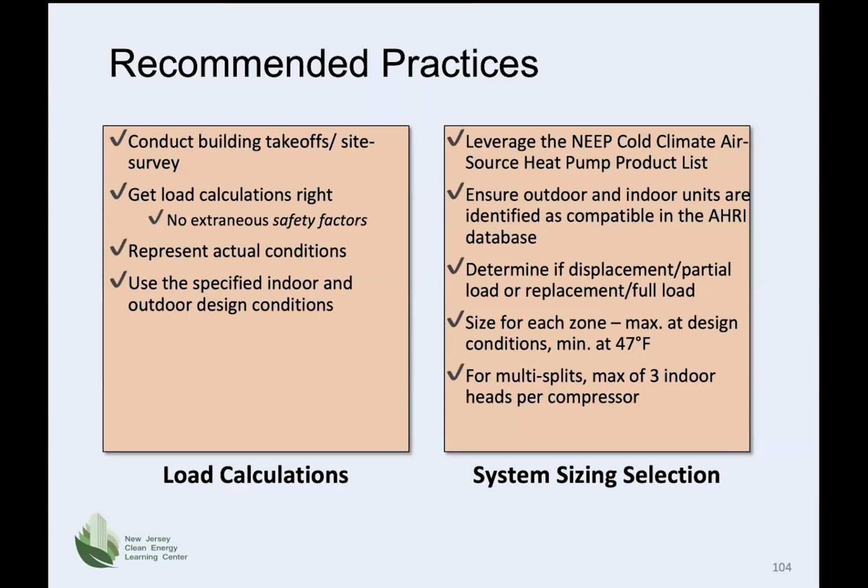And then determine whether you're going to displace part of the load or whether you're going to replace it in full, whether you're going to retain perhaps the legacy system and use it as a supplemental or backup heat, or if the entire house is going to be heated with the heat pump. And then each zone should be looked at at the maximum design condition. And for mini splits, the recommendation really is to never exceed 3 indoor heads per compressor.